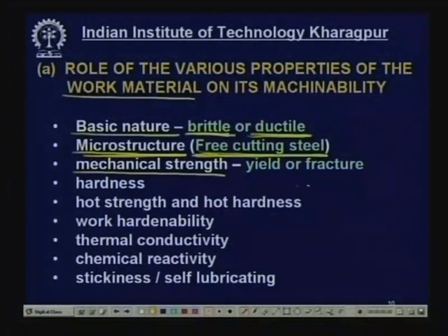Now, mechanical strength. It is obvious that if the mechanical strength is very high, the cutting force will increase and the consequential problems also increase. When you say strength, it is yield strength for ductile materials and fracture strength for brittle materials. Hardness: if the workpiece is very hard, then it will be difficult to machine and the machinability will be reduced through an increase in cutting force, cutting temperature and wear. The tool will undergo wear very fast.